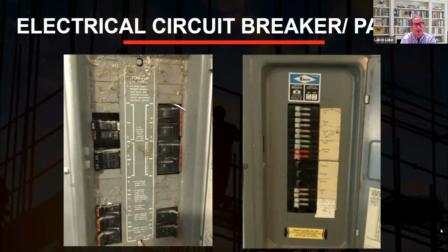What happens is there's still electricity in the wire, and the circuit breaker is not stopping the circuit. And what happens, the arcing occurs and fires start. So not really a good condition. Okay, so remember, Federal Pacific Electric Stab-Lock. That brand was commonly used in single family houses and also condominium buildings built in the 60s and 70s.